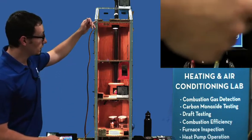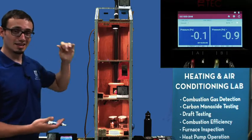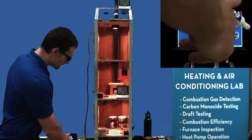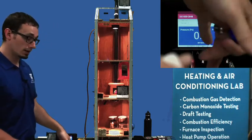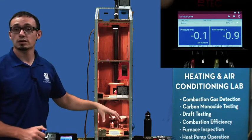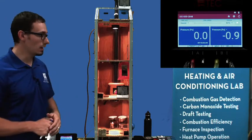And the further you get away from that neutral pressure plane, again, the more marked those pressures are going to be. So down here at the bottom, I'm seeing a negative 0.1 and negative 0.9. That's a huge increase in pressure. So that's going to pull more of those contaminants into the house in this scenario.